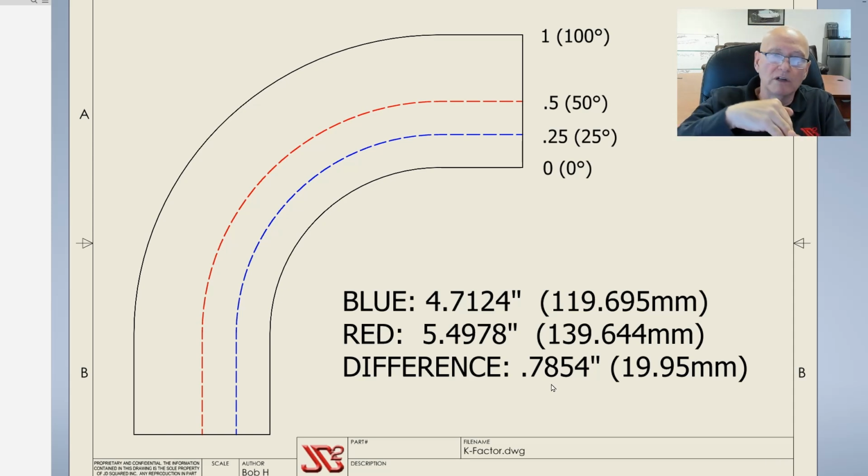So generally, once I measure a bend using the string and nail trick I told you about in that video, I will then fine tune my parts by changing the K factor. Because the K factor is the thing that's going to change more dramatically if the heat treatment of the material changes. The bend radius, yes, it is going to change. The harder the material, it's going to spring out a little bit further, but in our experience it doesn't seem to be as pronounced as the K factor on the overall accuracy of the finished part, the length of the finished part. So you can see right here a big difference why you want to do that.